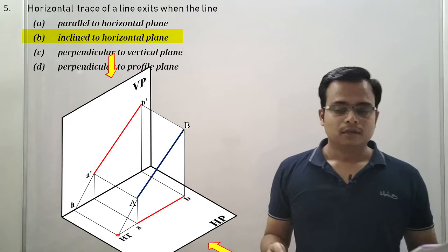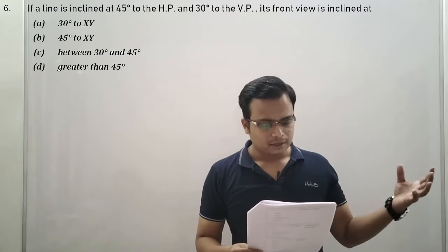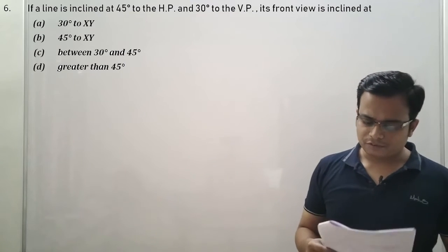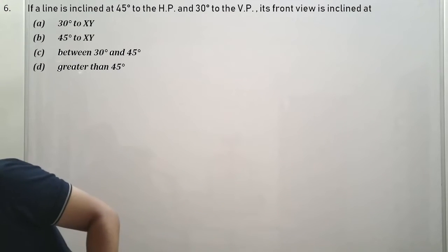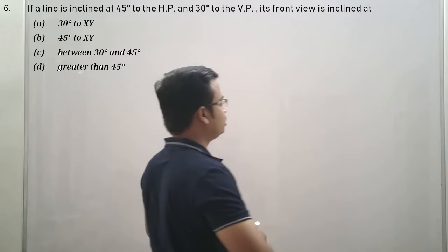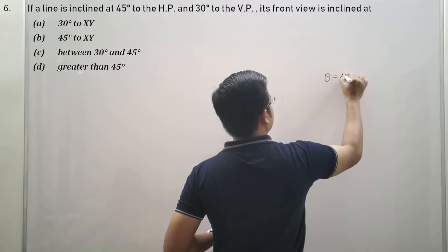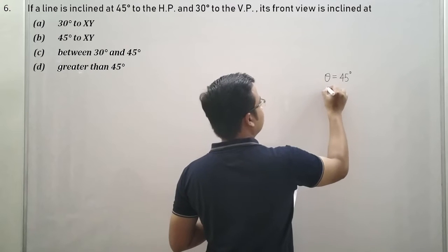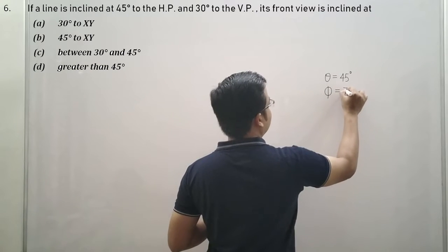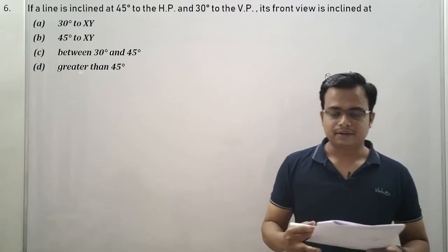Done. Let's move over now to the next problem, problem number 6. Very interesting. Let me read that for you. If a line is inclined at 45 degrees to the HP, any angle associated with HP is theta, that is 45 degrees, and the inclination of this line with VP is 30 degrees, phi is 30 degrees. The front view is inclined at...